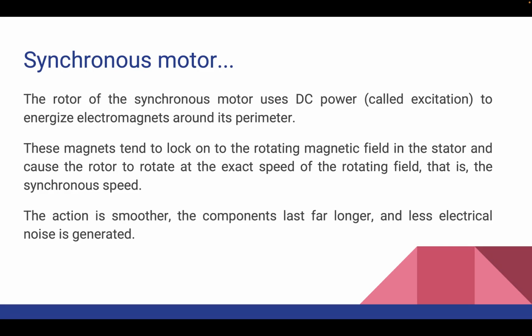This difference in construction ensures a continuous and smooth electrical connection between the stator and the rotor, allowing for the transmission of DC power, which is necessary to create the magnetic field in the rotor. So we learned that a synchronous motor requires slip rings and brushes, and its assembly is slightly different from the DC motor.